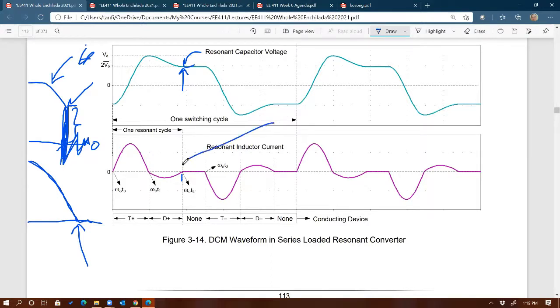So here we have the benefit of operating the resonant converter in DCM, because we're able to use PN junction instead of Schottky's. Couldn't you just use a Schottky in series with the PN to get the high voltage rating? Oh wait, no, because it's as slow as the slowest. Yeah, exactly. You're dragging down the Schottky by putting it in series with PN, so the fast diode is useless because it's dragged down by the slower diode when it turns on and off as well.